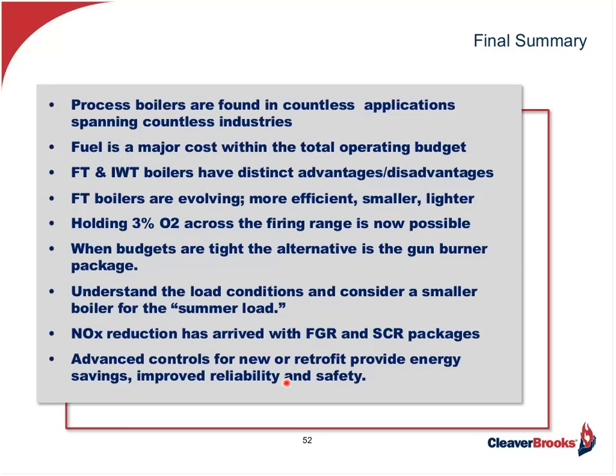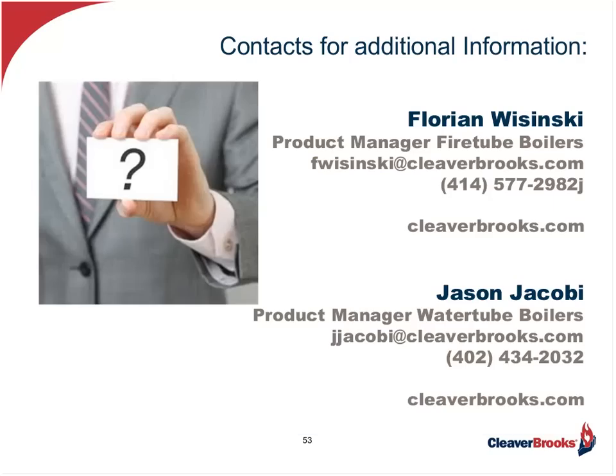Understand the load conditions. I can't stress this enough. And consider a small boiler for the summer load. Keep those boilers running at the sweet spot as much as you possibly can. NOx reduction has arrived with FGR and SCR packages. And advanced controls for newer retrofit provide energy savings, improved reliability, and safety. So now let's open it up to questions.